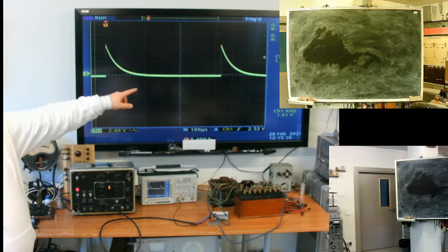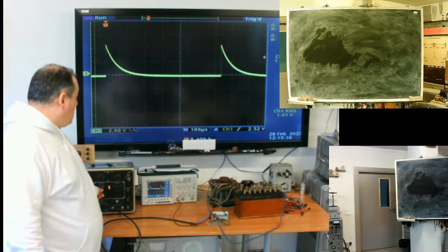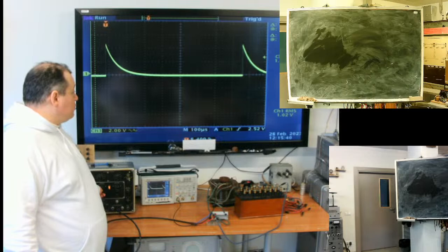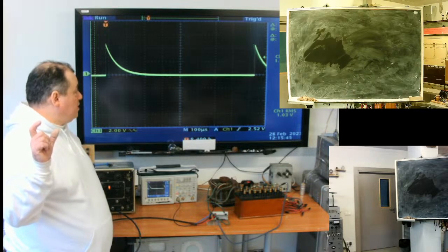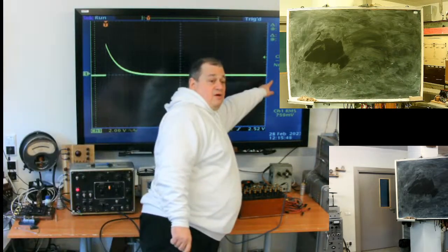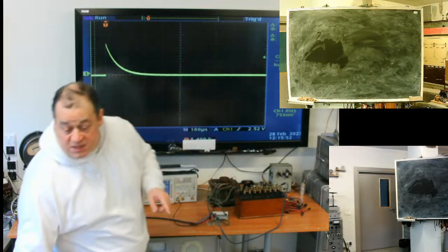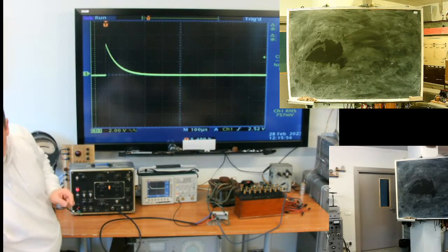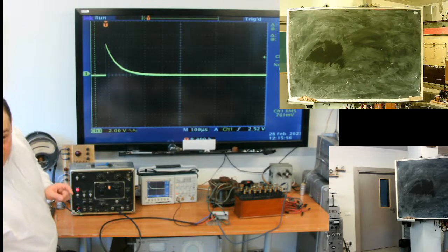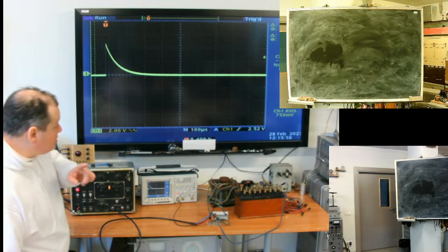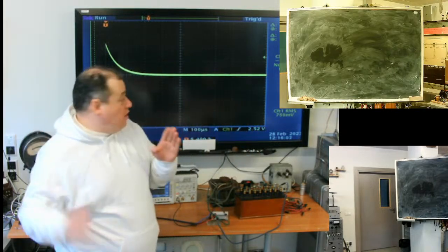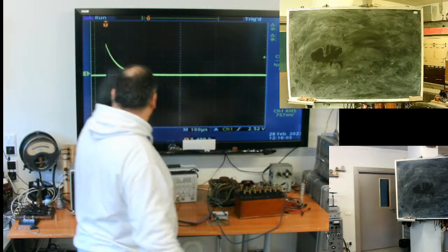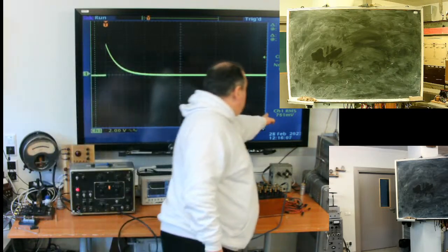Signal is periodic. What am I doing? I'm shifting the time span. No period found. For my scope, at this moment, the signal is no longer periodic. Why? Because the next pulse occurs outside of the observation window. For my scope, time starts here and ends here.